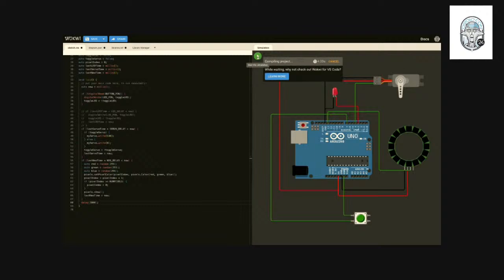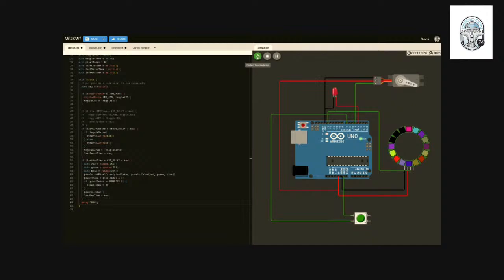Now everything happens every 1 second. It prevents all the other code from running at the same time. So, you might have parallel things going on. You have the servo moving at a different time than your LED, or the fact that you want to be able to read the button or the ring, but everything is now gated by this delay that's here.